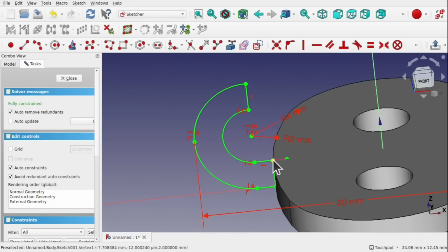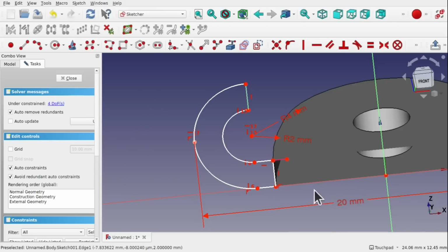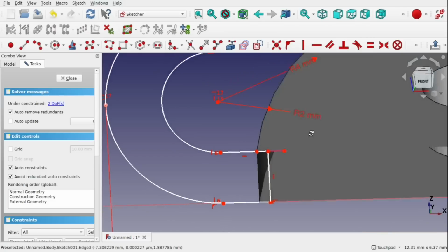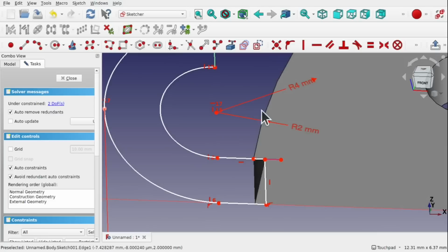So I'm going to release this point from this line by hitting delete. So let's come over to the sketch, back to view section, and see what's happened. I'm going to take this point and push it inwards. And also take the bottom point. These points have become unconnected, so I'm going to take this point and make those coincident. So now I've pushed this in, I can push it further into the material to compensate for this arc.